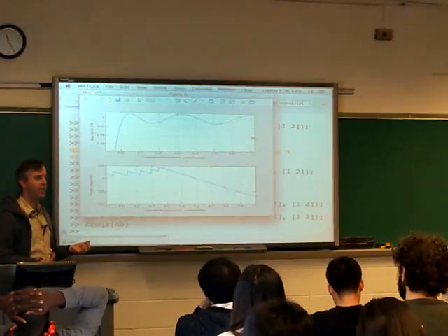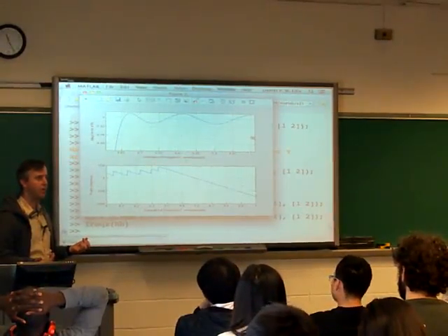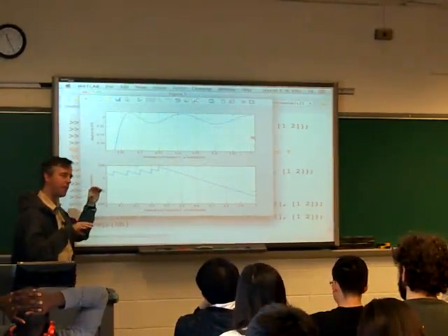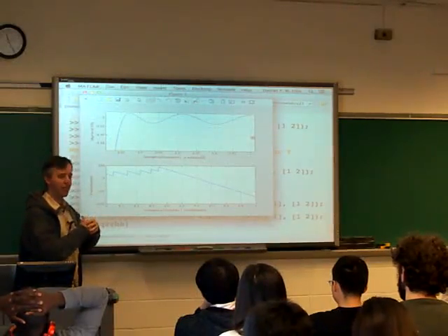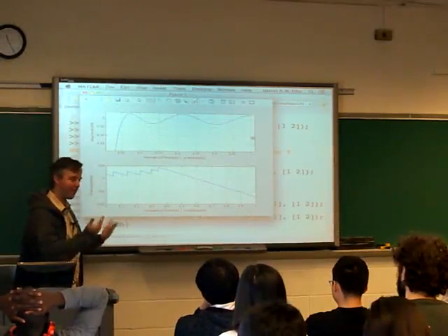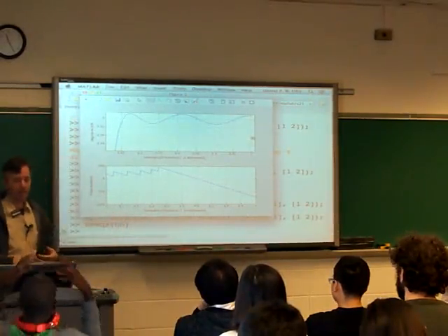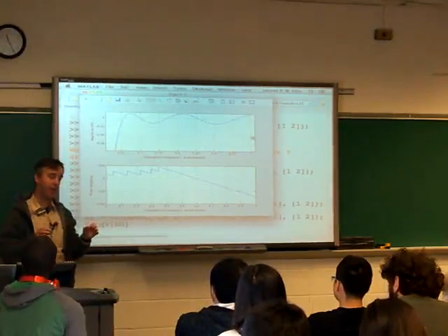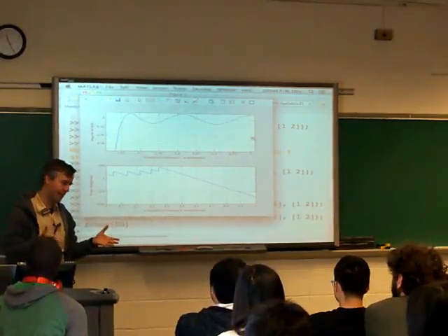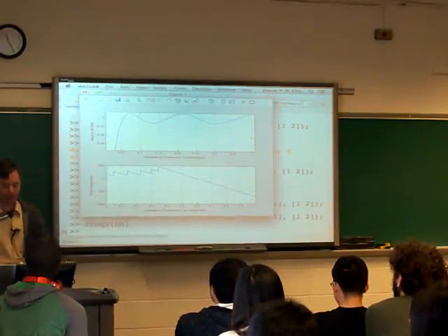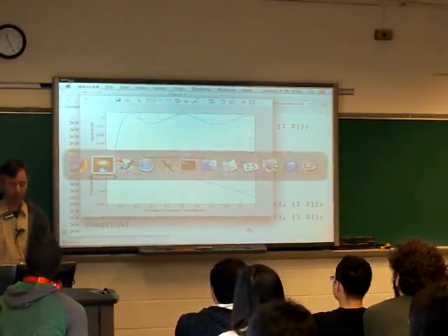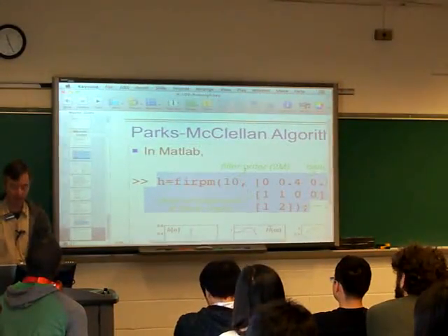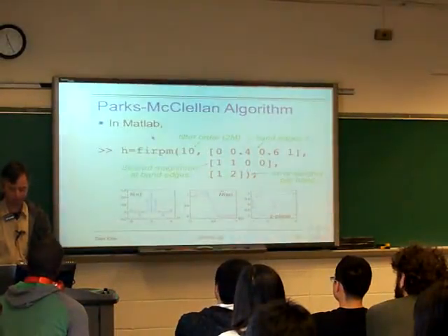How does that, in the elliptical filter specification, you didn't specify the transition band, right? You specified the ripple depth and the pass band and the stop band, but then it just got as narrow a transition band as you want. Here we have a different set of criteria that we actually specify in our process. I'm sure there exist techniques where you specify the ripple depth and it gives you the filter and sets the transition band, but the natural way to do it here is to work from just the filter edges and then have the error be as large as it needs to be.